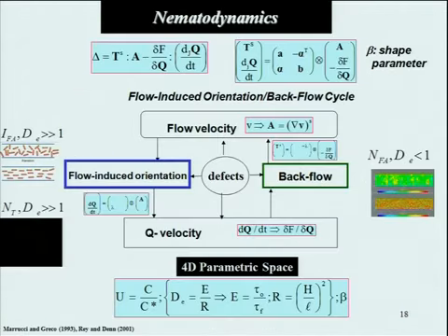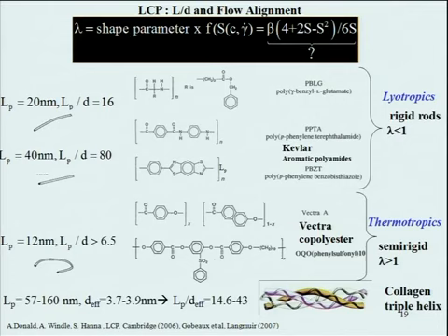So now you have a nematic and you do nematodynamics, right? And so the key point, you do nematodynamics like we do, flow-induced orientation, right? You introduce a flow and you create a flow-induced orientation. So this is a useful approach in the isotropic phase. So introducing flow-induced orientation in the isotropic phase gives you a so-called paranematic phase. That was the first experiment. And the second experiment is, again, do cone and plate rheology, but in the nematic phase. So the key point is this.